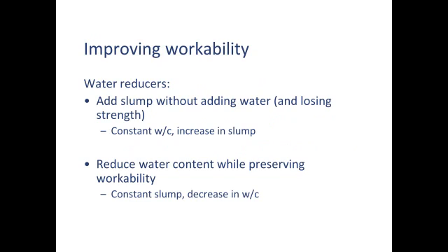There's another way to think about it. When you're starting with your mix, you can achieve a very high fluidity or very high slump, but instead of having to use a lot of water to get there, you can add this water reducer and then use less water to achieve that high slump. So you're really talking about two different sides of the same coin. We can add workability to an existing mix, or we can develop a mix that uses less water to achieve a given degree of workability. And that degree of workability can be very, very high if we wanted to.